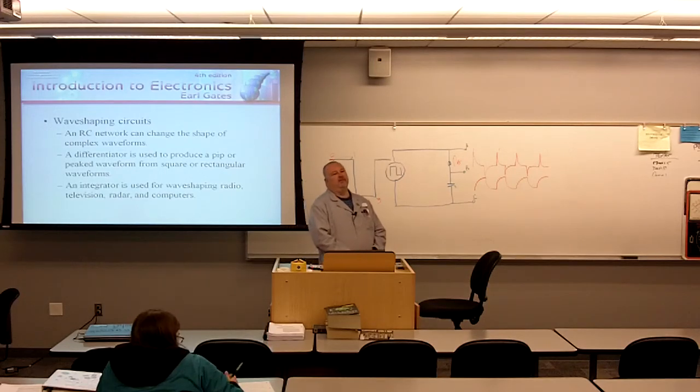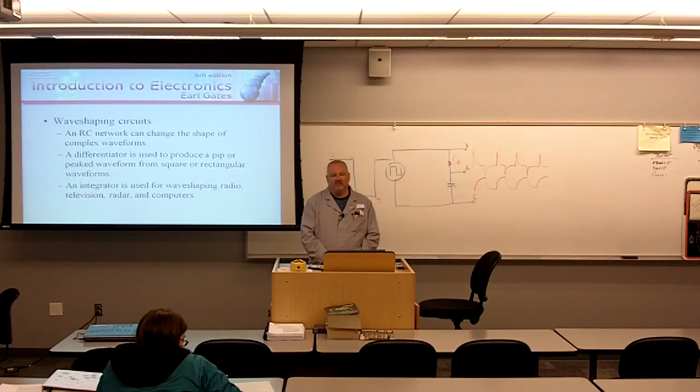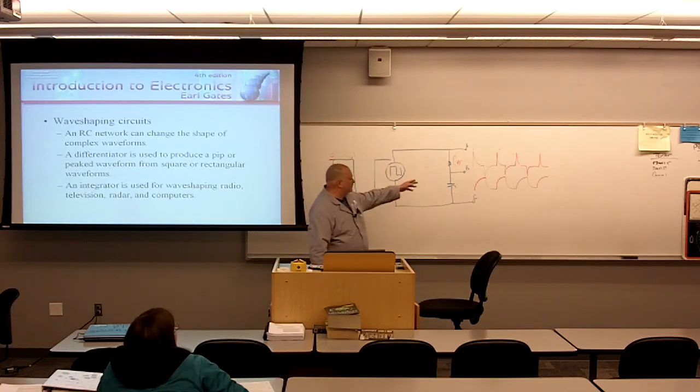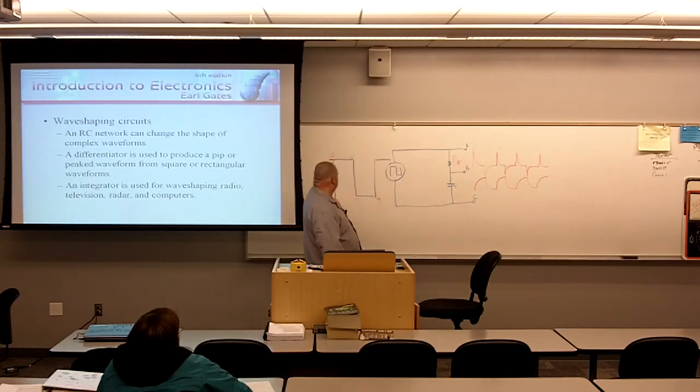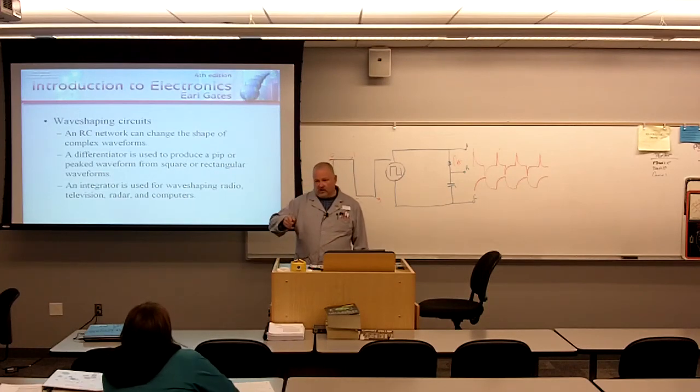If you get screwed up on your quiz, and you will, if you get screwed up on your exam, and you will, if you get screwed up on a job interview, draw this down on scratch paper. It's a series RC circuit. How is it going to behave? When I slam this with a square wave that basically is DC voltage, off, 100%, hold on, off, how's it going to work? It's going to charge a capacitor up, but it's going to take time to charge a capacitor up. As the capacitor is charging,